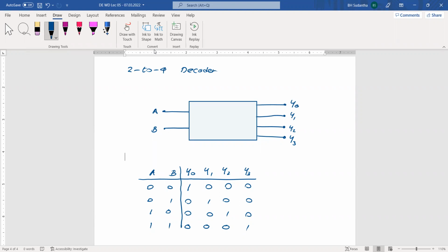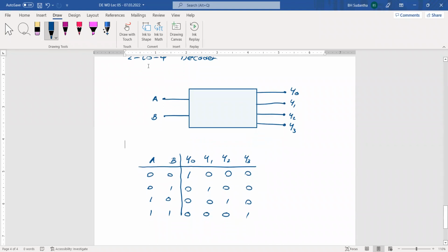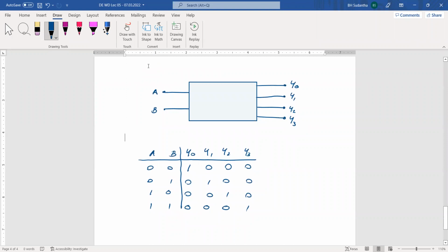Okay. But when you want to design a combinational circuit, whatever the type of circuit, so far we have discussed, what are the steps of the standard designing procedure? First, we identify inputs and outputs, then we draw a block diagram to show those things. Then, understanding the conditions, we prepare a truth table to include those conditions.